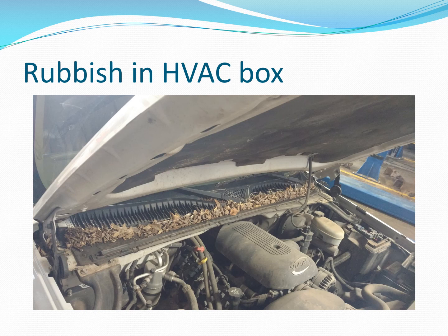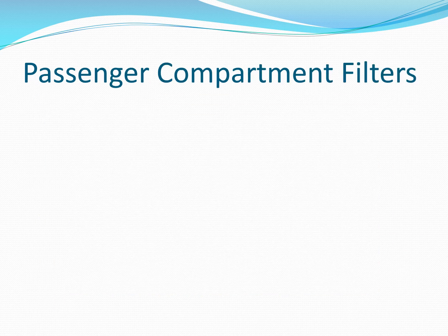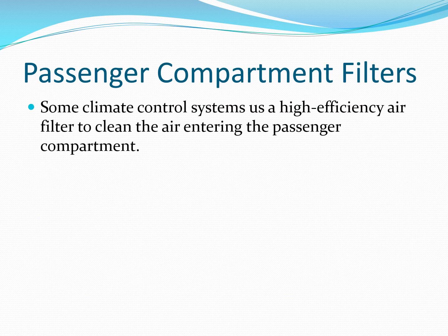If this grill work is all covered up with leaves and debris, and for a person that parks outside on a regular basis, this is a very normal condition, then these vents can be blocked. That's a possibility. Or that debris, as it gets crushed and put into smaller pieces, is going to fall through those cracks and actually go into the heater box or the box inside the dashboard. And then we've got other problems and blockages. This could create blockages in airways, and this also could create blockages in the passenger compartment filters.